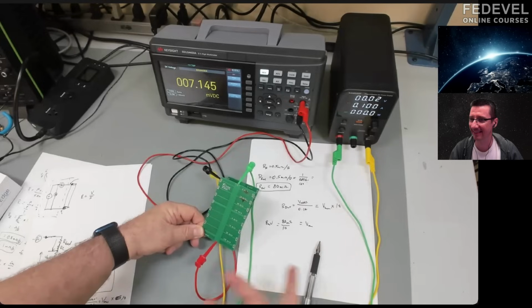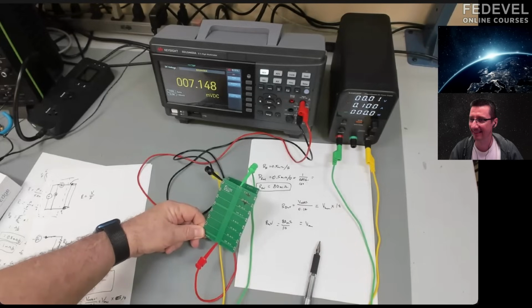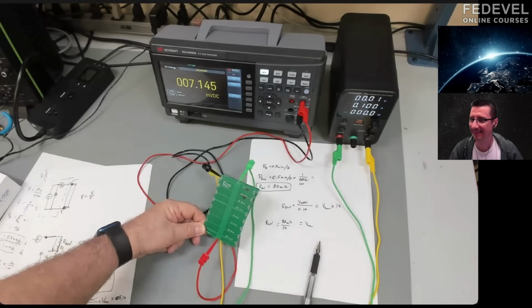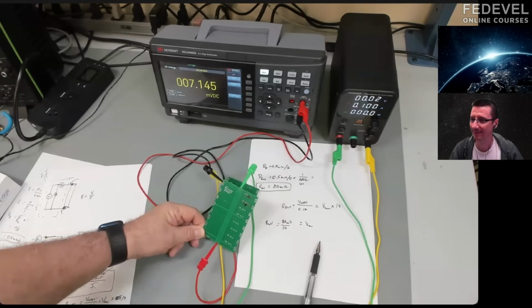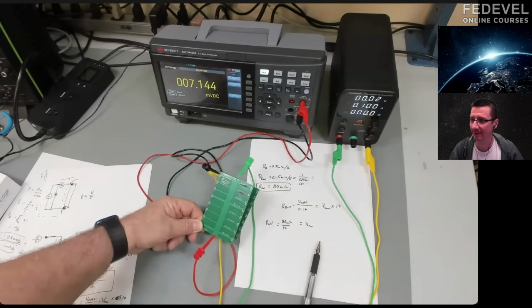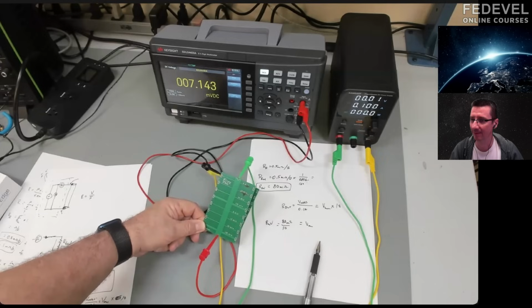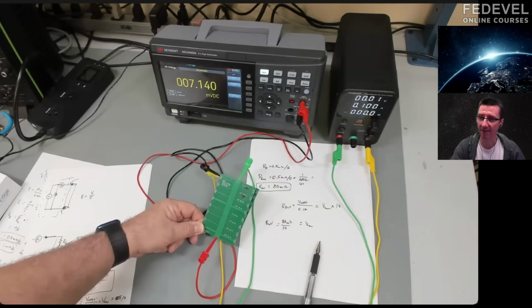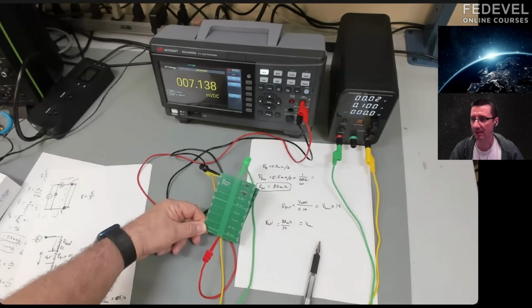So depending on the board that we've got, and depending on the lot and the processing it went through, this is a lot closer to what we expected of the 8 millivolts for 80 milliohms, because I think it's not as overplated as the other one. Could this also be a different PCB manufacturer? Nope, same fab vendor.